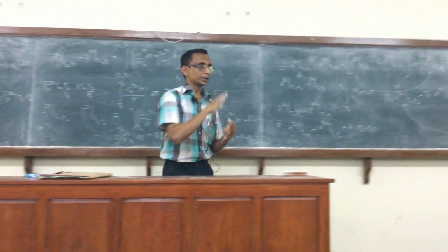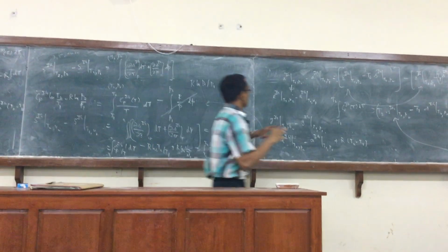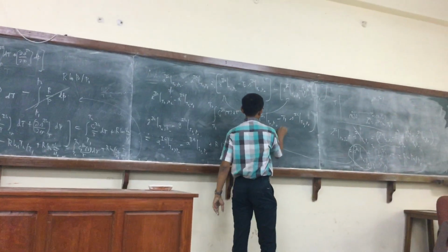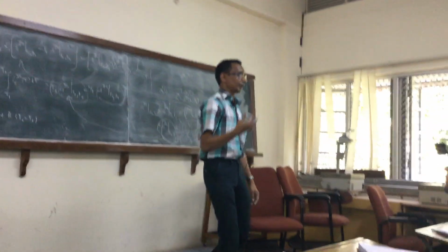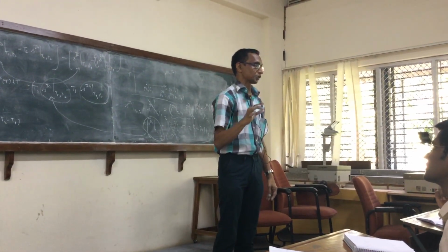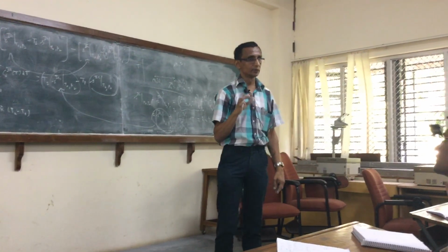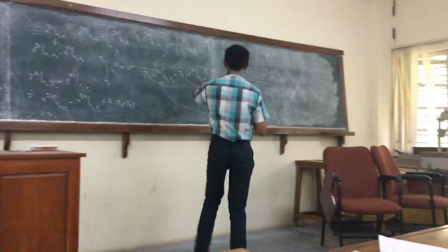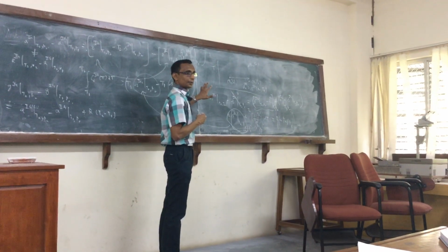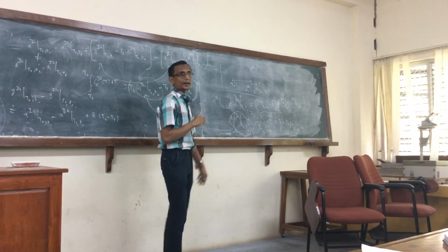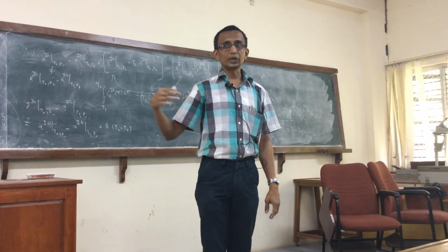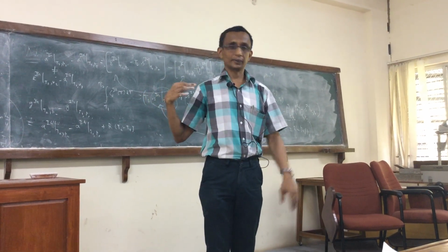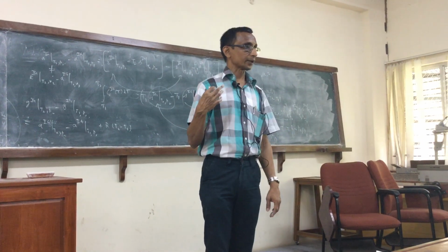Certainly this would be sufficient for the internal energy, enthalpy and entropy, but for A and G we would in turn need the entropy of the ideal gas at some given temperature and pressure. Right? That is very important. Now let us give it at some T0, P0, arbitrary temperature and pressure. You can certainly use the same idea to calculate the entropy at P2, T2 and P1, T1 in terms of that. So that is an additional quantity that I need.